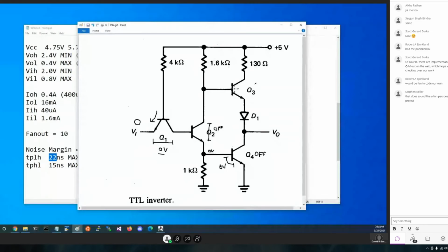Well, I would take a different approach to it. What you're saying is going to work, but sit here at the base. We know we can't go this way, right? This transistor's off. There's a cut path there. We can't go down. If I follow backwards, will I ever get to voltage? You should. Oh, look at that, I got 5 volts. Because I got 5 volts, that means current can flow. If current can flow, as long as I can get enough, this is going to be 0.7 volts.